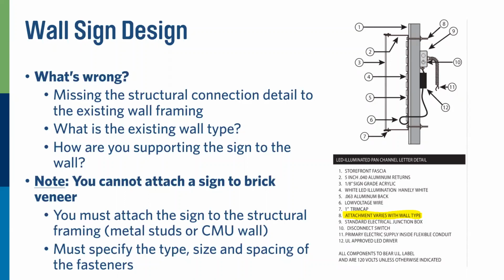You cannot attach a sign to a brick veneer. It is actually not allowed by code. It's been that way forever. And I know people do it all the time, and I know there's a lot of signs attached to walls. But in general, you cannot attach a sign to the brick veneer.